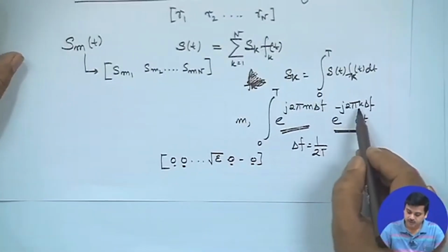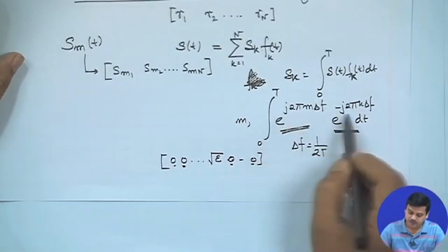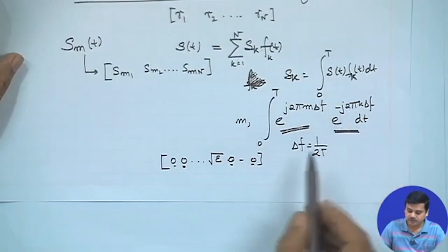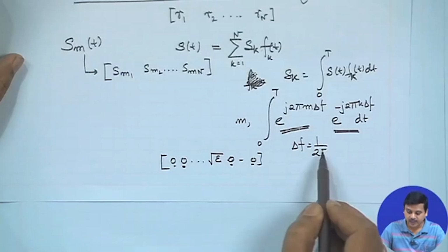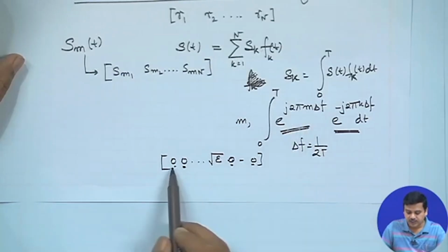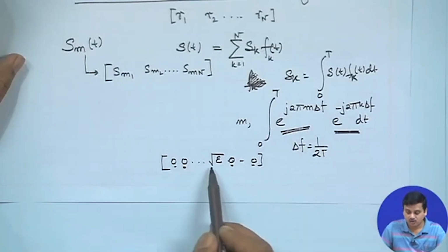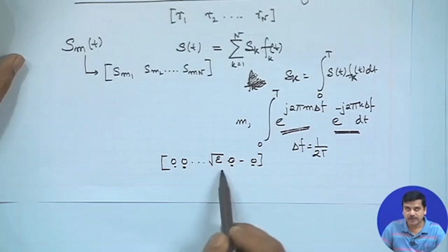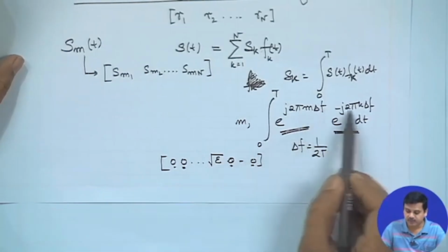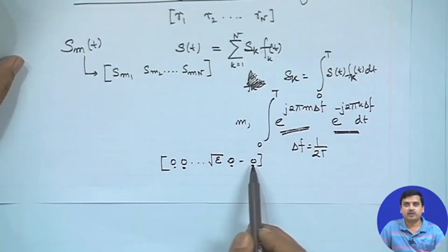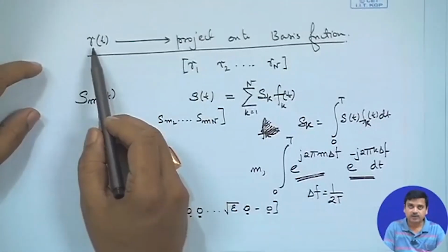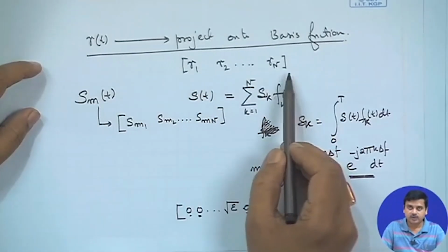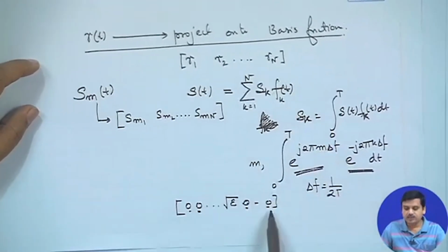different signals. So, once you do this projection, by virtue of orthogonality, which we got with delta f equal to 1 by 2T, then the projection could be zero in the ideal case on all other signals. There would be energy in the desired component when m is equal to k and 0 again on the others. So, that means the projection of R(t), when you break R(t) into these components for M-ary FSK, in the ideal case you would get like this.